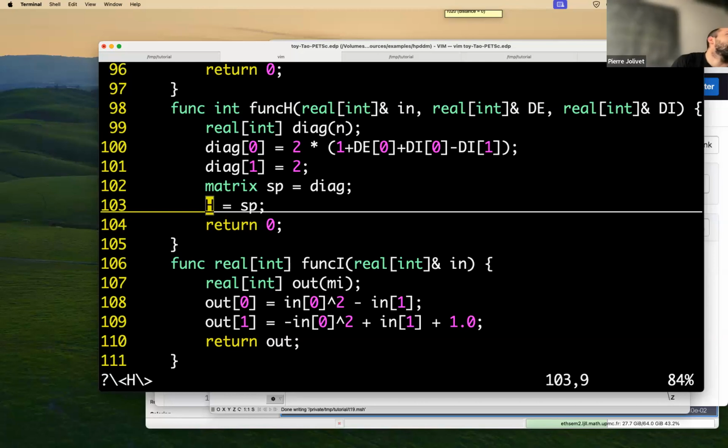Question about Dirichlet boundary conditions. In FreeFEM, you use on, and also you use a huge number, so you somehow specify TGV, and it's a huge number. But can you just input or specify the values, and not solve, not including it in the matrix? Is it possible?